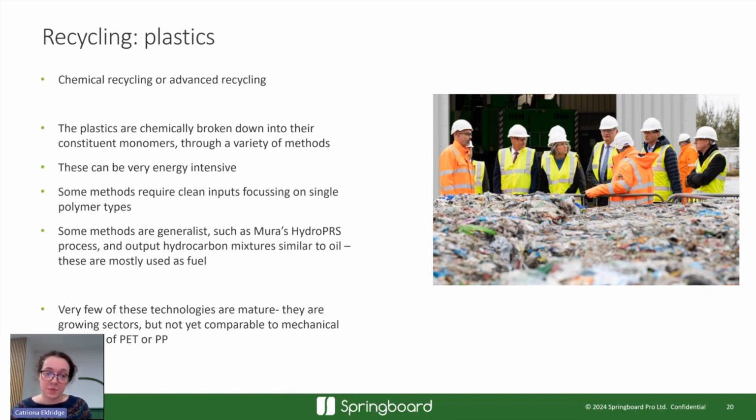Some methods, specifically pyrolysis and steam hydrolysis, are more generalist. So Mura actually fairly recently opened a site in the UK. They've got another one in Korea, another one in Germany, another one in the States. And what they have is a steam hydrolysis based facility, which should be able to take a mixed input. They claim to be able to take in pretty much any kind of unrecyclable plastic. And what they do with that is they then use hydrolysis and high pressure to break that apart into a hydrocarbon mixture of fairly short chain molecules. The output is very similar to oil. These generalist methods don't give you a polymer out the other end. They give you a mixture that's in behavior and appearance really quite like crude oil.